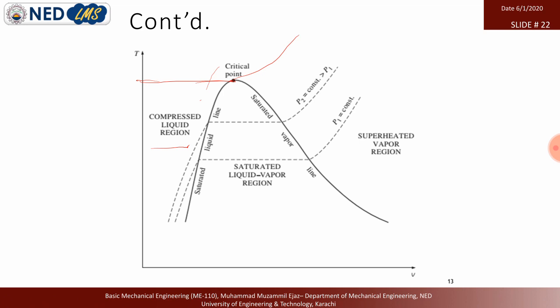Also we are minimizing the vapor region which can form fog later in the turbine, where the liquid in the steam hits the blade and erodes it, which is dangerous. So we are minimizing the risk as well as the time, and we are also increasing the efficiency after going to the supercritical region. But of course it costs money.